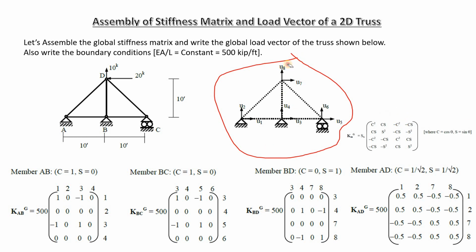Okay, another thing that we need to know right now is the bearing angles and how to consider the bearing angles. For example, when I am developing a stiffness matrix for, let's say, this member. So this member, this is the AB member. So am I going to call that the AB member and conduct calculations like that, or am I going to call that BA member?